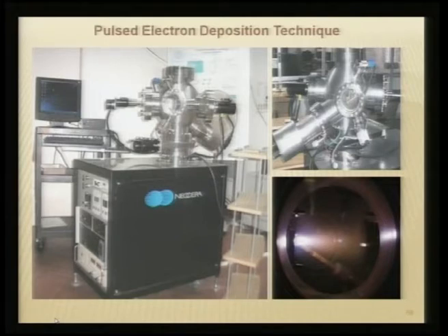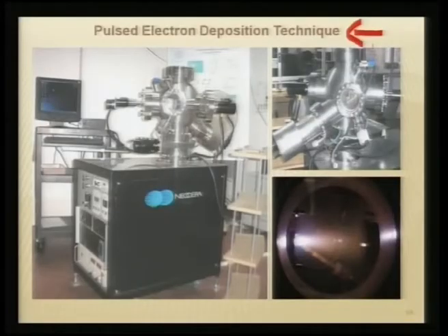Just 2 more slides and I would finish. Suppose you try to completely use a physical vapor deposition technique, as I have already discussed in module 3. This is a very viable route. If you take zinc oxide commercial powder or any other powder synthesized by wet chemical routes, you can try to make films of zinc oxide using this technique.